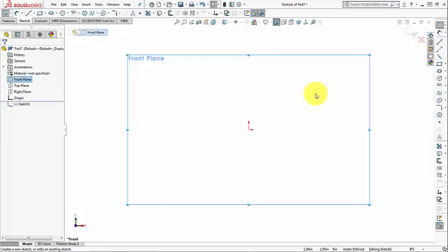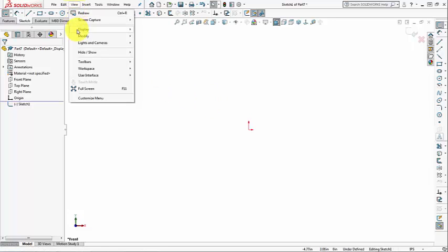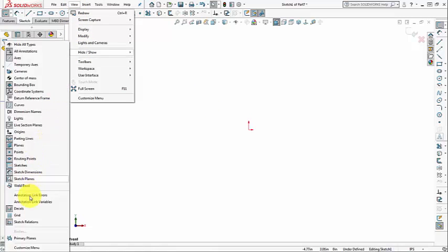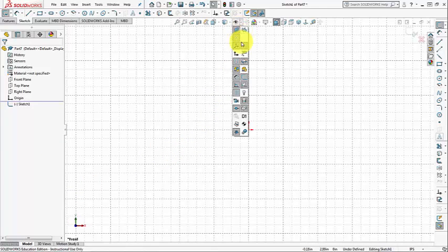When starting out in SolidWorks, it can be easy to confuse Edit Sketch mode with Edit Part mode, so utilizing these indicators can be especially helpful. Grid Display is another sketching tool that can be used. This simply helps you gain a frame of reference when sketching. You can toggle the grid display on or off from the View menu, Hide Show, Grid. The same result can be obtained from the Heads-Up View toolbar, Hide Show Items, View Grid.